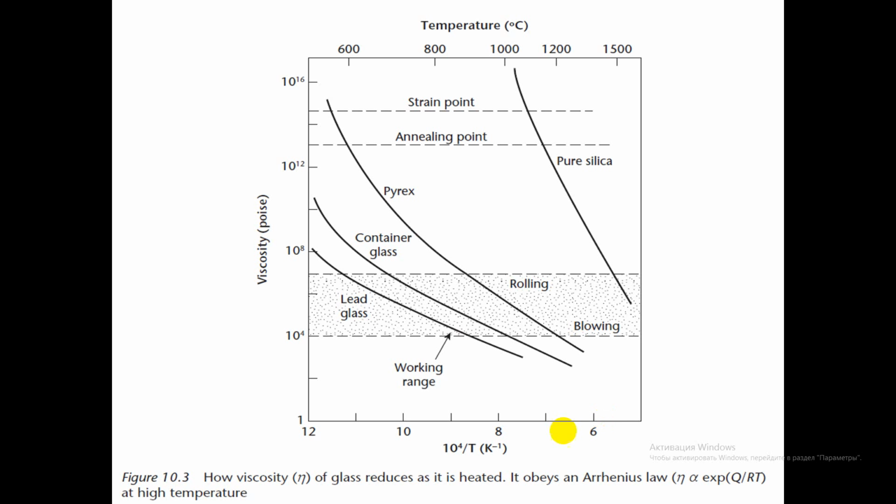The strain point is the temperature at which any internal stresses are reduced significantly in a matter of hours. The annealing point is the temperature at which any internal stresses are reduced to a commercially acceptable level in a matter of minutes.